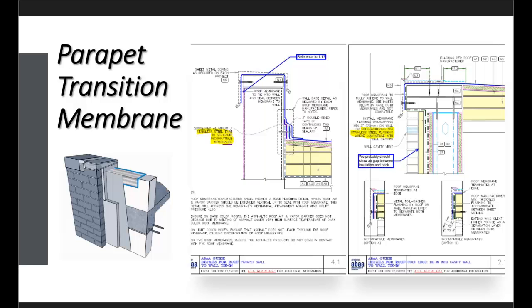It's one of a couple things that they were considering. Is it compatible? Yes. The longevity of the material, if you're going to recommend something to bring two products together, you want to make sure that it's going to last long. And because of the compatibility, it really helps ease the sequencing of trades. Like I said early on about testing your peel and sticks in both directions, you never know who's going to now be installing on top of the other one when originally we thought it was going to be the other way.